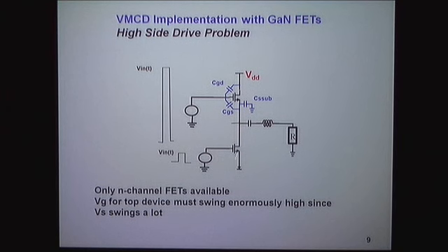So here, well, you may only have to drive to minus 2 volts. Here, if you really want to do it without a floating drive, you get these ridiculous voltage swings. You do not want to drive this to, let's say, 2 volts below 48. You will simply waste all your power in the drive, and it probably wouldn't last very long. So we certainly don't want to use just that simple method, because this is not like 3.3 volt CMOS. This is something closer to 48 volts. So we'll need to solve that problem.